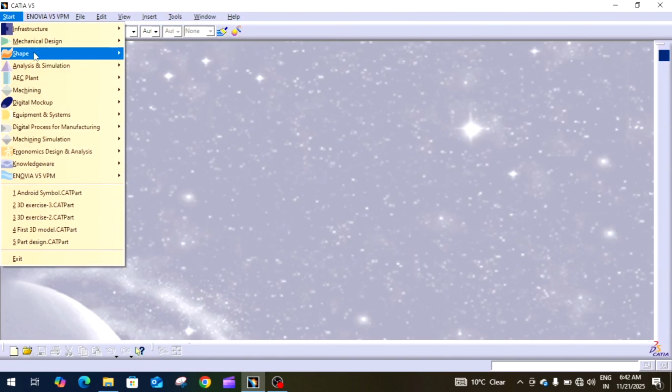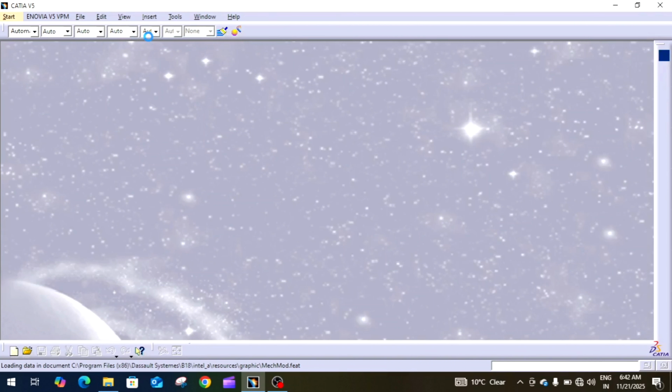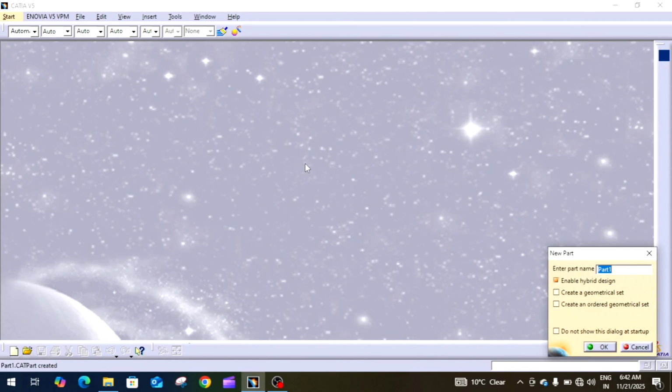Go to start, mechanical design and part design. Rename the part as dress up features, and click on OK.